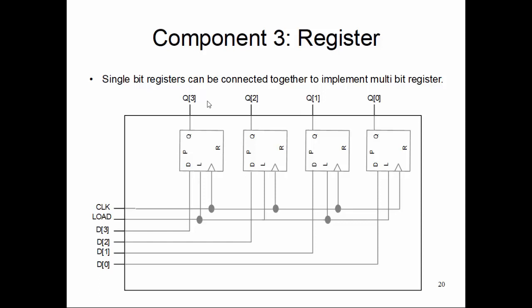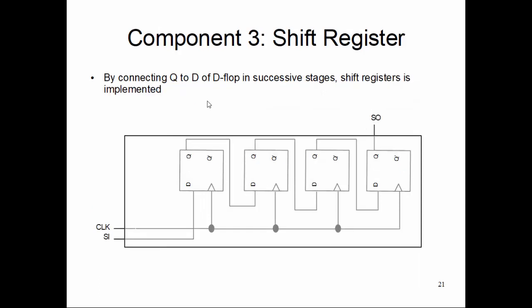Now let's talk about something like a shift register. Remember, a register has this ability to shift left and right, shift left logical SLL, shift right logical SRL, that kind of instructions, and how we can implement it. So let me introduce you to some special type of register called a shift register. To start with, let's forget about the 1-bit registers. Let's just deal directly with the flip-flop.